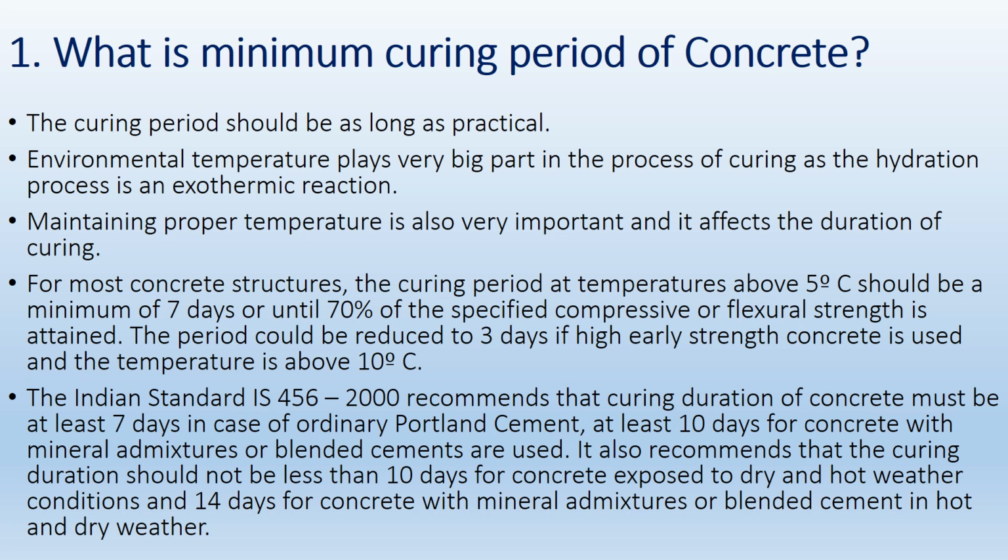The Indian standard IS 456:2000 recommends that the curing duration of concrete must be at least 7 days in case of Portland cement, and at least 10 days when mineral admixtures or blended cements are used. It also recommends that the curing duration should not be less than 10 days for concrete exposed to dry and hot weather conditions, and 14 days for concrete with mineral admixtures or blended cement in hot and dry weather.